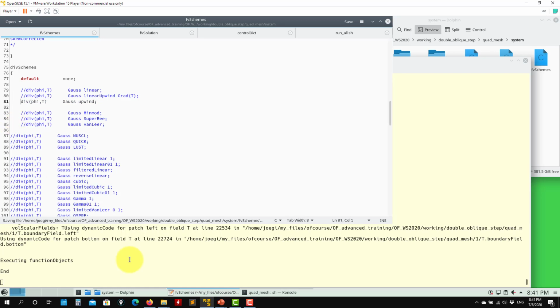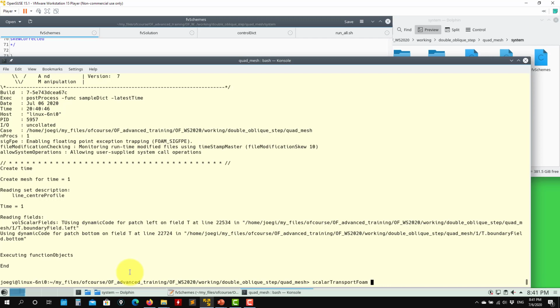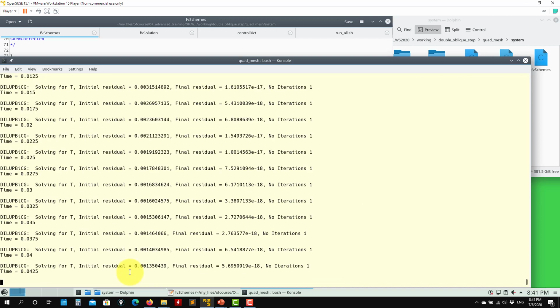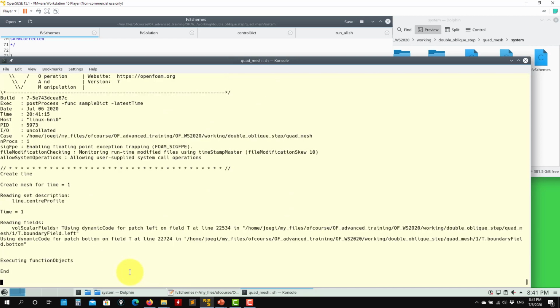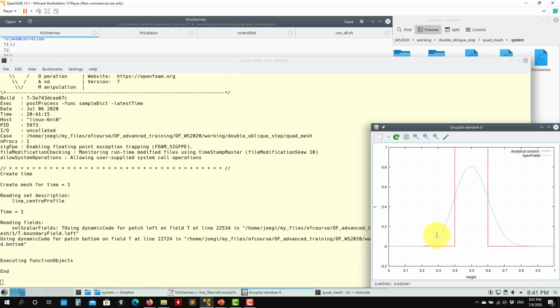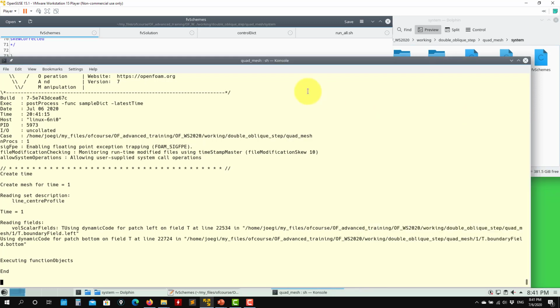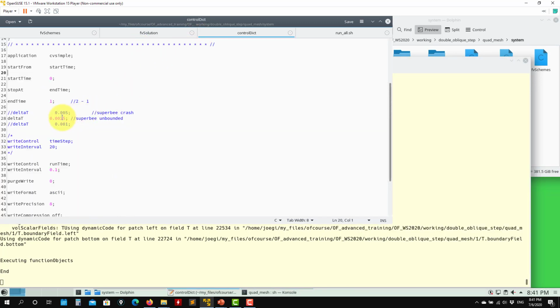So now we go to the Upwind. We know that the Upwind will always work, but the problem is that it is highly diffusive. If I now do my sampling, see that it is incredibly diffusive. It's too much diffusion that you are adding. And just to show you the fact that I told you that it will always run.